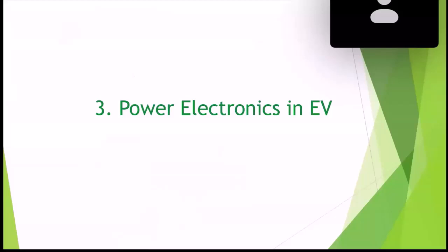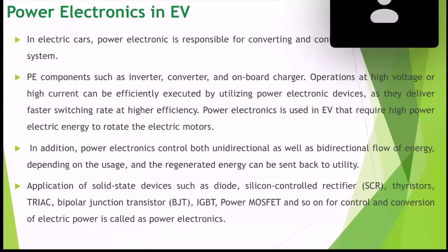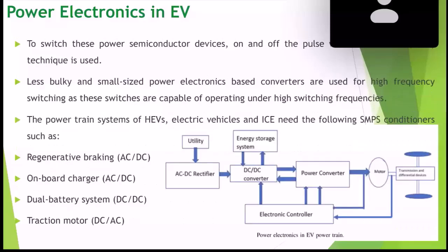Not only motor control operations, but in the electric powertrain, power electronics has a wide application, starting from inverter, converter, and onboard charger. A variety of solid-state device based systems are used for controlling or operating the powertrain system. For example, regenerative braking requires an AC to DC converter.